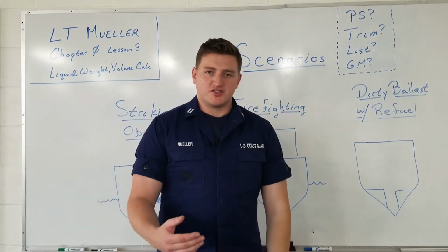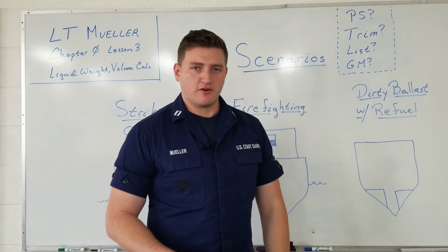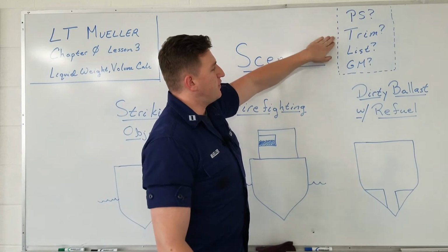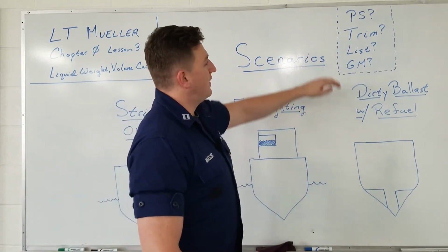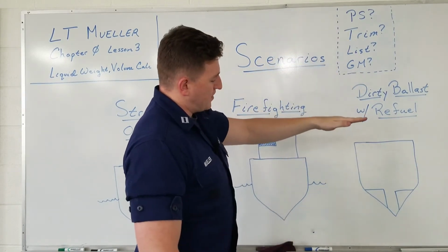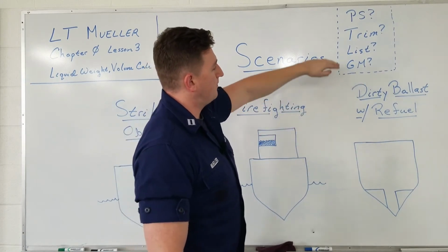However, I just want to show you that with every single addition or removal of water or fuel or any type of liquid load, you're going to have several different things you're going to have to consider, and all of these are critical to the ship's stability. PS is parallel sinkage, so that's if you have a ship that sinks completely parallel, or there's also parallel rise, where it comes straight up out of the water.